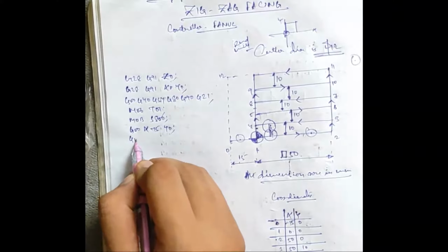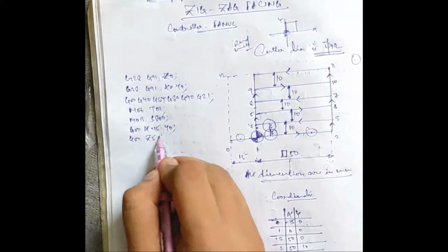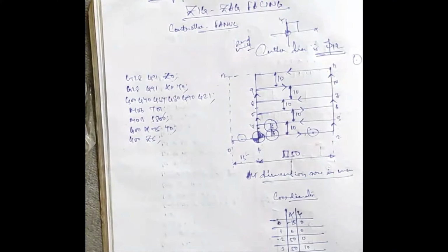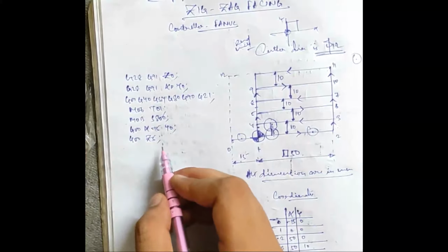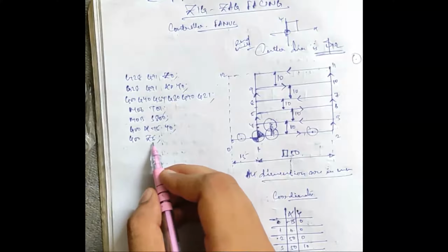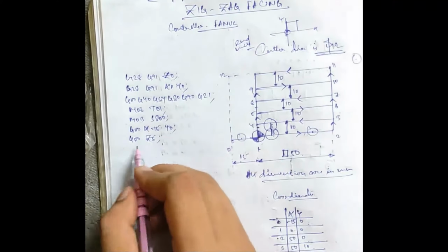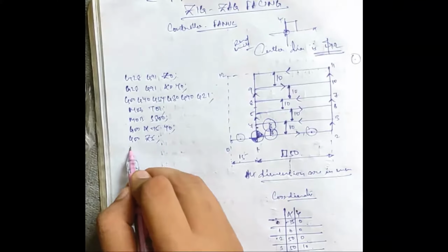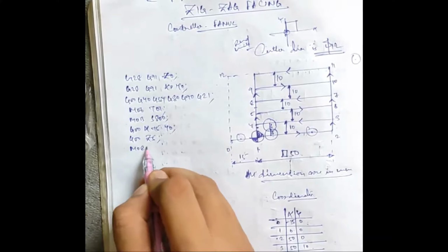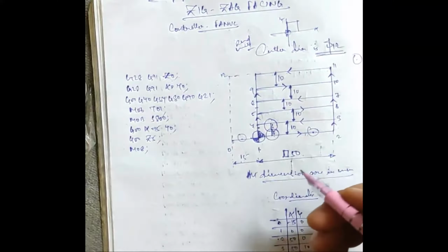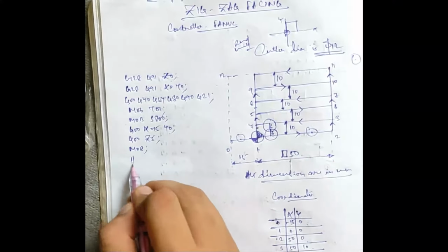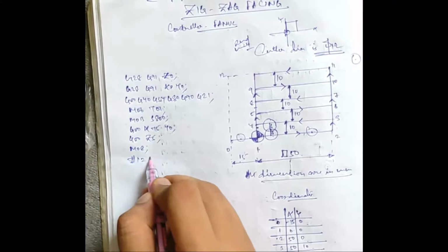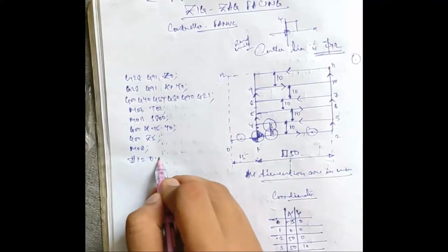Then G00 Z5. Okay, then after reaching a height of 5 mm, let's turn on the coolant, M08 in milling. Okay, so after that H1 equal to, let's take 0.5.